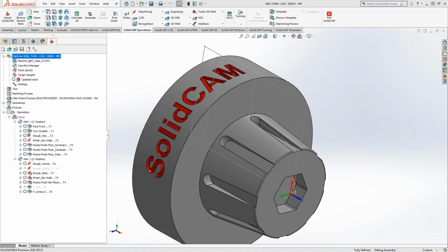Yeah, so this kind of goes along with what Mark was just talking about. So for his pocket, sorry to take this more, Mark, if you want to go. No, so when we're using iMachining, iMachining has the three geometry types in there that are all recognition feature, automatic recognition feature. So what it's going to do is look at the stock of what's already done from all the previous operations and adjust the toolpath from there.